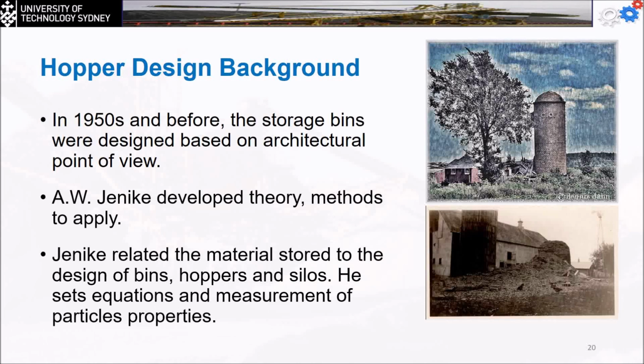So Jenike, the same person who had invented the shear test for the material, developed the theory and methods to apply for the design of the bins. Jenike related the material stored to the design of the bins, hoppers, and silos, and he set it in equations and measurements of the particle properties. That's why we had the lecture for the particle properties and characteristics in the first week, because everything we're going to do from now on, we are going to call back the characteristics of the material we're going to use.